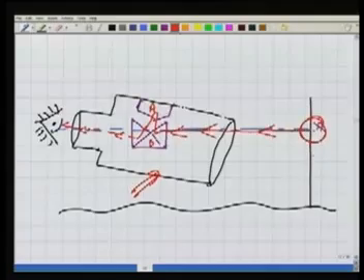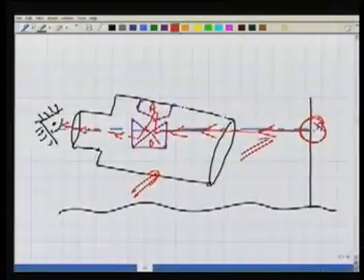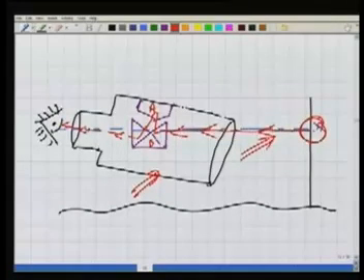So what is the meaning of that? The meaning is, even if my telescope is slightly tilted, it doesn't matter, because the optical assembly inside is ensuring that the line of sight is horizontal, is ensuring that the reading that I am reading corresponds to the horizontal line of sight.